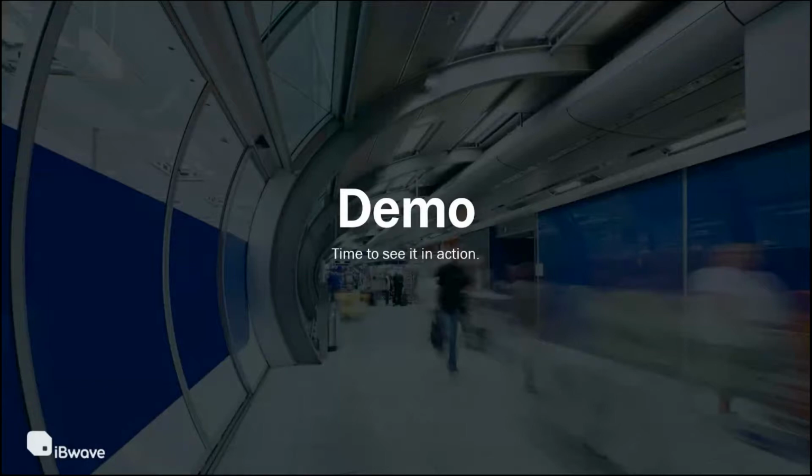Okay. And is it passive and active survey or active only? Well, both. Passive right now for cellular, passive and active for Wi-Fi. And like I said, the active might work for cellular if you have the active survey server on the same LAN network as your private LTE network. We haven't tested that, so I can't guarantee it would work, but technically it should work. And in the future, maybe we will look into doing some throughput test of your LTE connection, but it's not available now.